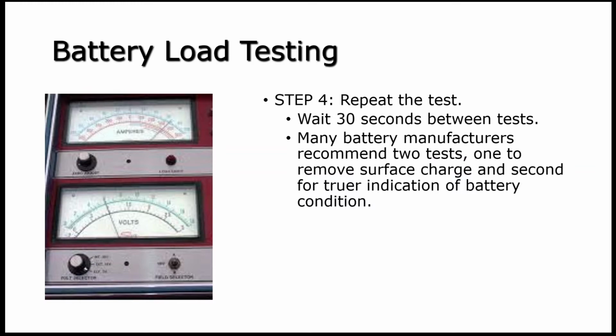So if you're going to use a capacitance tester and you have surface charge to remove, use this tester. It gives you two baselines. It gives you a good baseline on the load and the ability to do a mass saturation of testing, right? And can it pass a mass draw on the battery? If it passed that, then you're great. Yeah, you got rid of the surface charge. Let it recover for a good 2 or 3 minutes before you hit it with a capacitance test. Manufacturers of capacitance testers are actually saying let it sit for 10 minutes before you hit it with a capacitance tester.